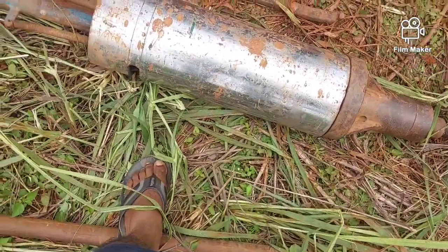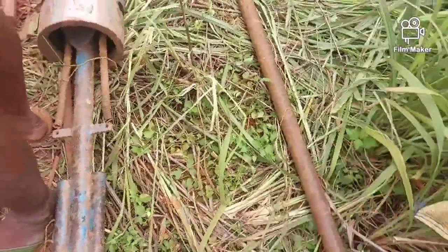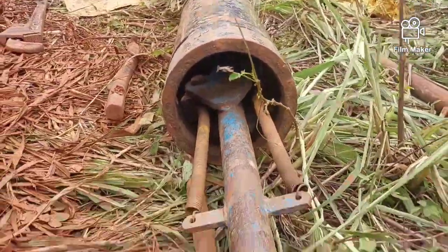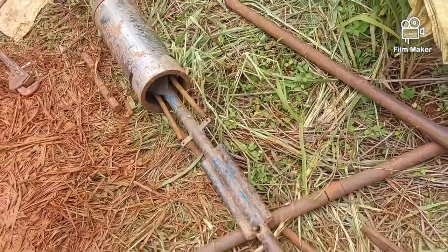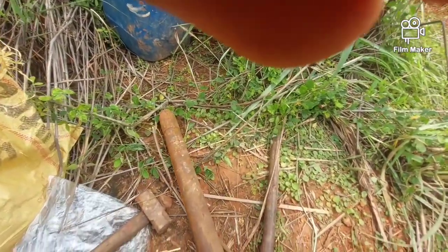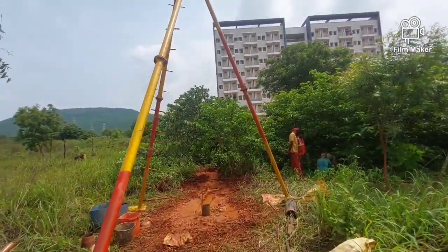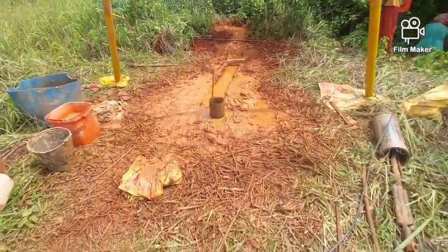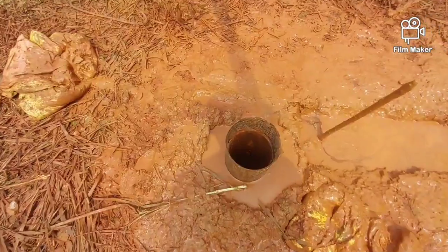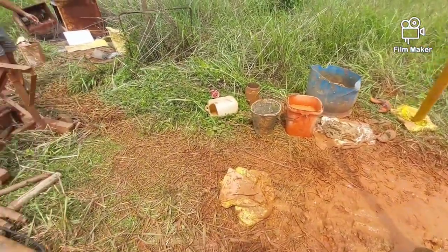This hammer has a 63.5 kg mass, and it is an auto trip hammer that free falls 760 mm automatically, though it is connected with a rope. This is the split spoon sampler, 460 mm long. Here the tripod is fitted at the point of the borehole, and a 150 mm borehole is created. The SPT tube will be conducted into the borehole and the sample will be collected from the hole.